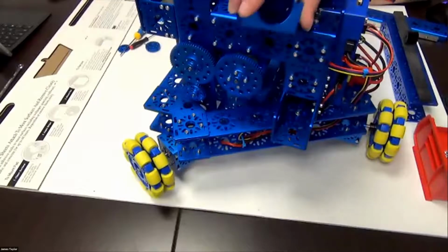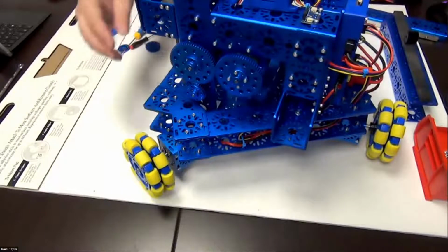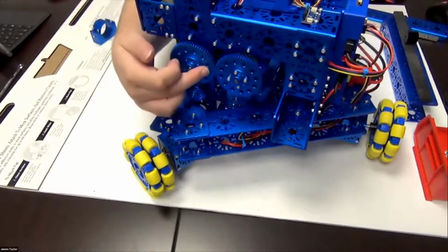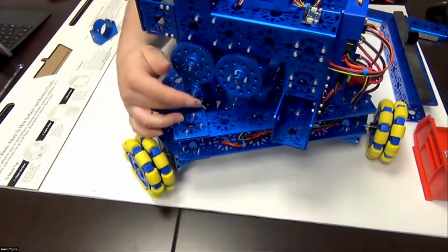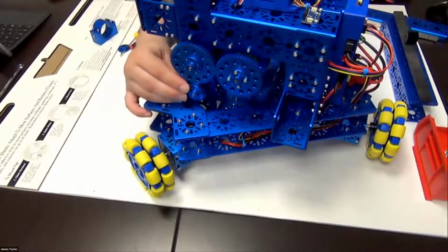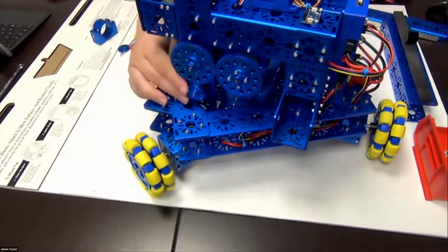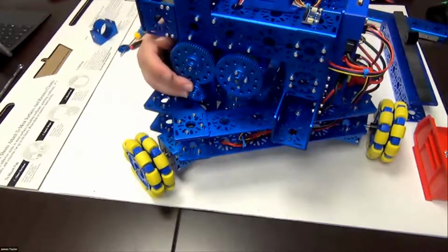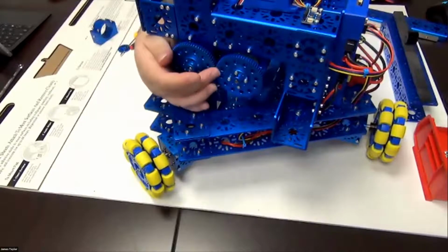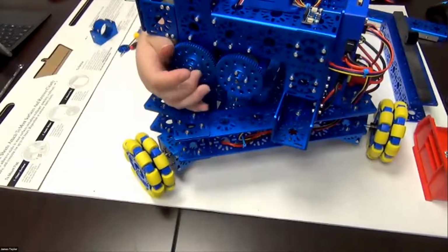And by using this mount, we can rotate the motor, which has this gear attached to it, so that it then meshes correctly with this gear on the elevator so that we can drive the output shaft. That's one of the benefits of having the offset shaft with the spur gear, and that's that we can rotate it inside that motor shaft and put it here.